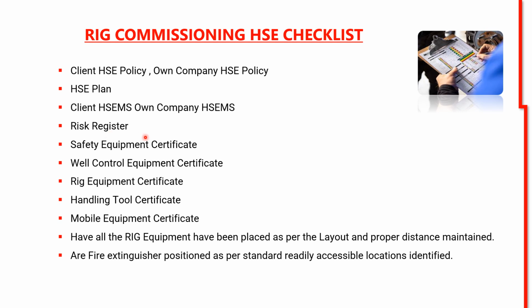Risk register, safety equipment certificate, well control equipment certificate, rig equipment certificate, handling tool certificate. It means the third party certificate. And if we are talking about the safety equipment certificate and the well control equipment certificate, it means the OEM certificate, the original equipment manufacturer certificate of those equipments.